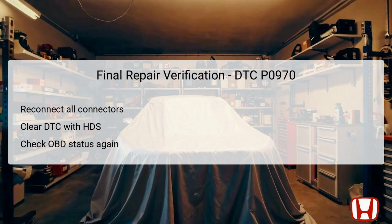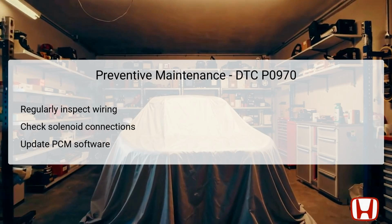Using the HDS, clear any DTCs recorded in the system to reset the diagnostic codes. Once cleared, start the engine and wait a moment before checking the OBD status for P0970. If the HDS indicates a passed status, this indicates success in resolving the issue, marking the troubleshooting process as complete. If it shows failed or not completed, further investigation into connections and previous steps may be required to ensure consistent operation. Effective preventive maintenance can help mitigate issues represented by DTC P0970.